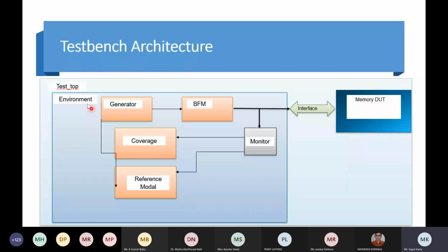Generally there will be small environments and there will be a top environment in an SoC. I'm giving you real industrial experience. You have 10 small environments, one for each interface like PCIe, USB, GPU, SPI, UART, and all those environments will be instantiated or would have a handle in the top environment. So the entire data from the top comes and then splits into the 10 different environments, and then it goes to this level. That is how it is done.